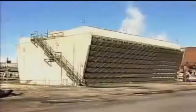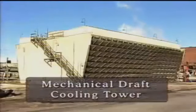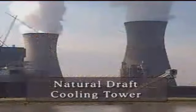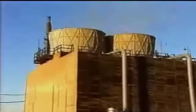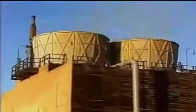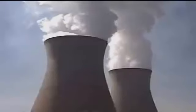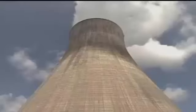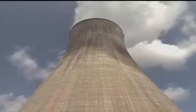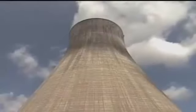There are two types of cooling towers that are generally used by power plants: mechanical draft cooling towers and natural draft cooling towers. Mechanical draft cooling towers use large fans to create airflow through the tower and thus cool the water. Natural draft or hyperbolic cooling towers have a chimney shape and do not use fans. Instead, they rely on the tendency of warm air to rise, sometimes referred to as the chimney effect, to cause the air flow that's needed to cool the water.